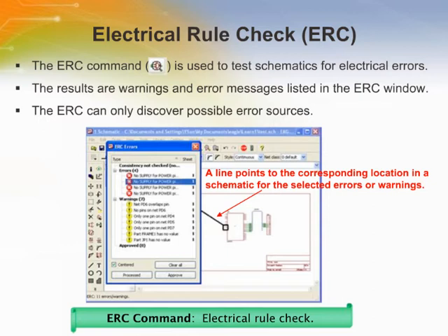A final thing that should be done before creating the PCB layout is to run the electrical rules check. This is done by the ERC command from the toolbar. This will check whether the pins designated as outputs are connected to inputs, whether there are obvious missing junctions, and so on. It also warns if you are connecting the supply bus inappropriately or if you forget to connect it at all. You should, however, know that an electrical rule check cannot guarantee that errors don't exist.